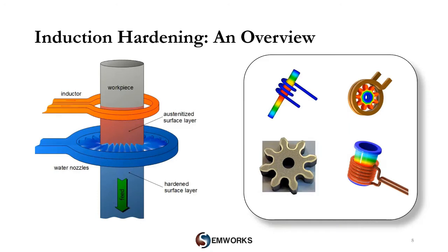This process of hardening is widely used to surface harden components based on induction heating, whereby the conductive materials are rapidly heated and quenched to induce martensitic transformation and then increase the surface durability and the residual stresses of the component. Unlike processes where heat is generated by an oven or a flame, the heat in induction hardening is created directly in the component. The hardening process can be precisely controlled by many factors, which will be mentioned during the next slides.